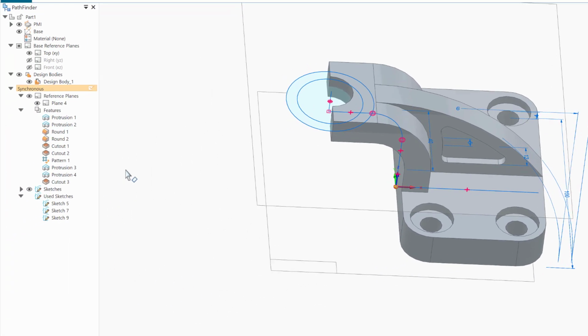Let me bring, okay, I have the sketch here. The circle disappeared because of the extrusion. So I'm going to click on the sketch again, right click, restore. So I have the circle back again. Okay, now since select is on, I'm going to click in the area inside between the 2 circles. So I'm going to click inside here, click on the arrow, symmetry.